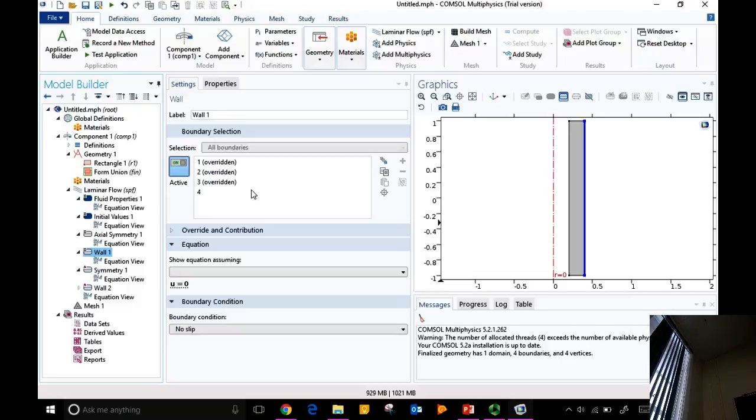You wait a little longer, keep rotating it, and momentum diffusion will take place from both sides. So it will become like this. You wait a little longer, it will become like this. And then it will become like that. Eventually it reaches a steady state, and then it stays there. So that is V theta as a function of R. It's essentially 1D. 1D steady state is this. 1D transient will be something like this.